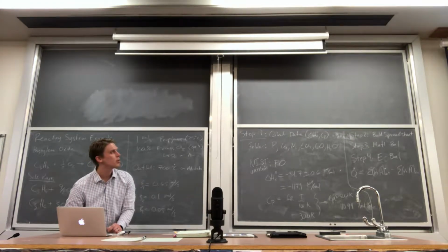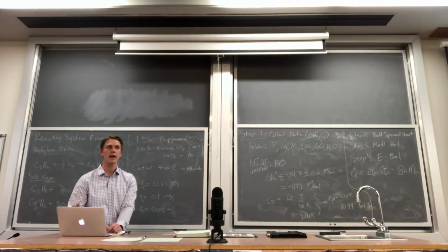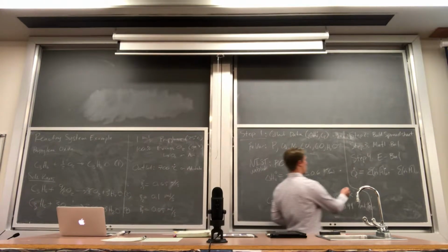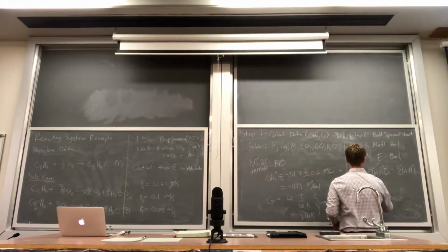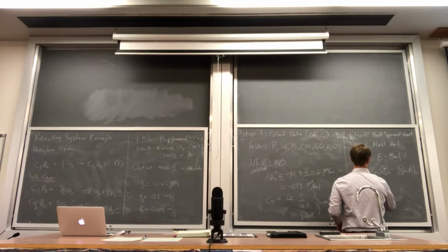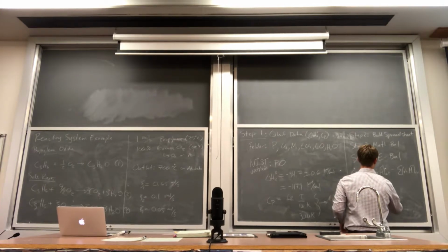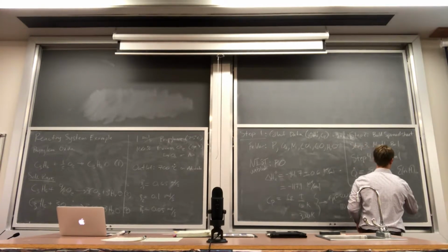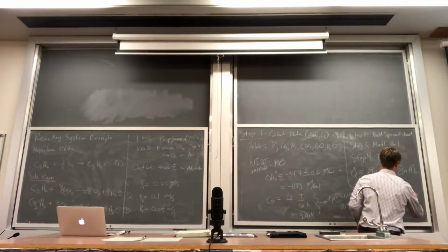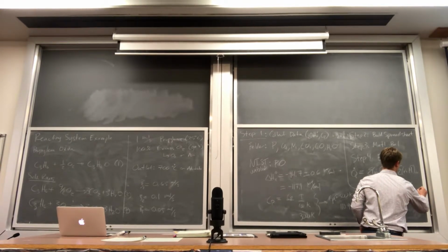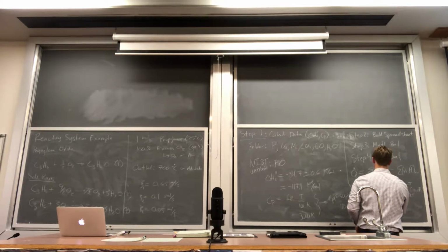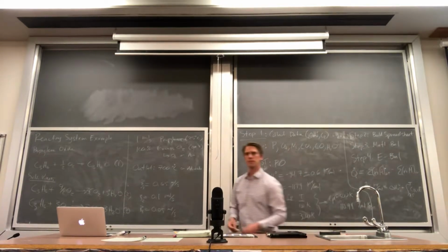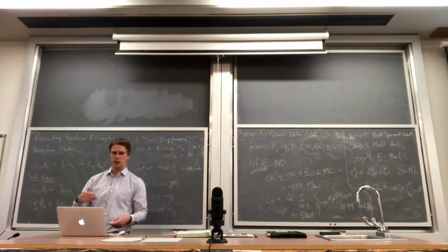This is the heat per unit mole, which is what we're calculating in the heat of formation method. Just to be clear, my H hats are in kilojoules per mole, and this is equal to delta H of formation plus integral from 25 to T C sub P of species i dT. Okay. All I've done is code that into my spreadsheet here.